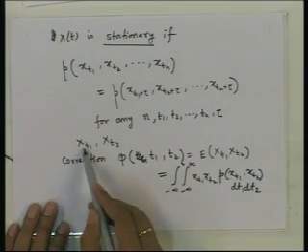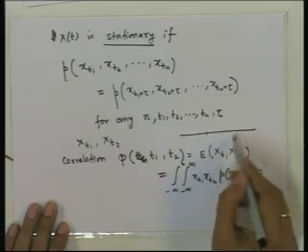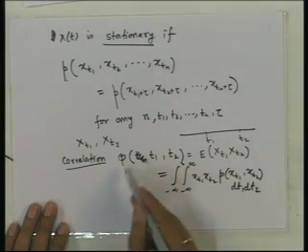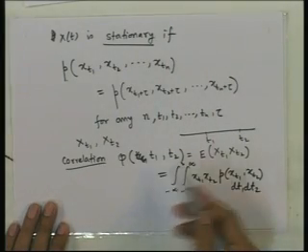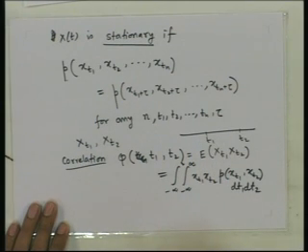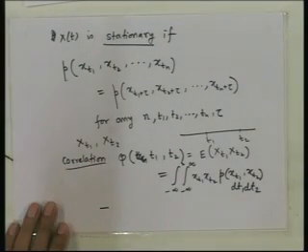Now, you have chosen two random variables at two different times, but if you change the two times, the correlation changes. So, this is a function of two variables t1 and t2, and this is called the autocorrelation function, because we have taken the same random process and taken two different time instances and computed the correlation between the random variables at those two different time instances.